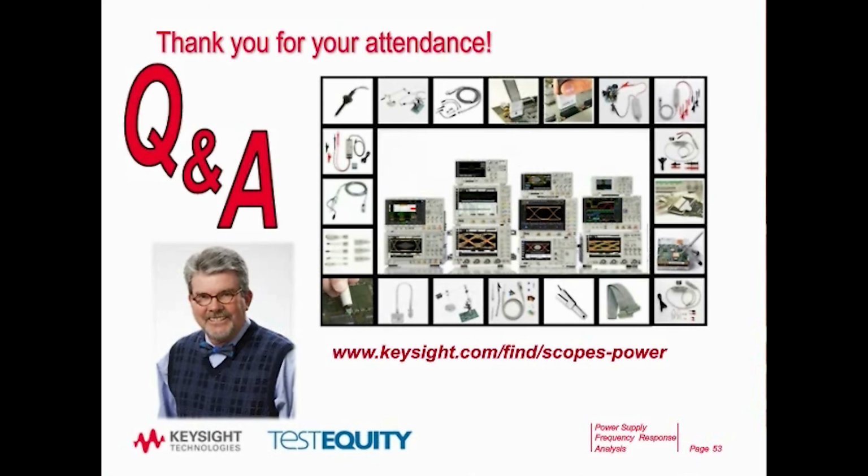Okay. How are you determining what amplitude to set the scope to for this measurement? Do you keep increasing it until it's valid? I think that's probably the best way to do it. I got these evaluation boards from PicoTest, and I asked Mr. Sandler what was the best amplitude to test these at. And then I did various tests at different amplitudes, and I observed the waveforms on screen to see when I started seeing distortion. The higher I can set the amplitude, the higher the dynamic range I can make, the more it pulls the signal out of the scope's noise floor.